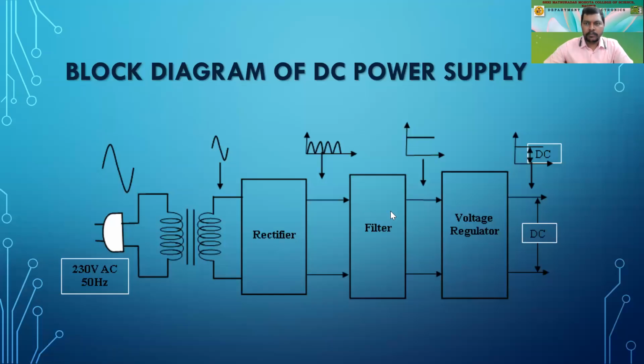So let me share this with you, the basic block diagram of the power supply that we are using. So we were here. After giving the transformer 230 volt AC, this is actually the step down transformer and it is going to reduce this AC voltage. We have applied 230 volt AC. Now it is being reduced to around 12 volt or 5 volt, right?